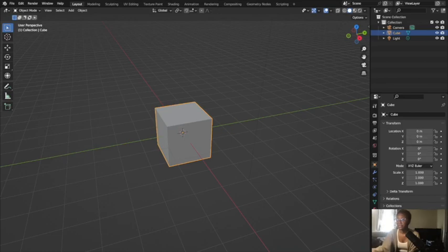The next tool I want to discuss is the cursor tool. So this will allow you to change the location of the cursor, which can be helpful when you're trying to frame a location for selecting something. To do that, it's going to be Shift and right mouse click, and that's going to allow me to drag my cursor to a different location if I need to reframe something.